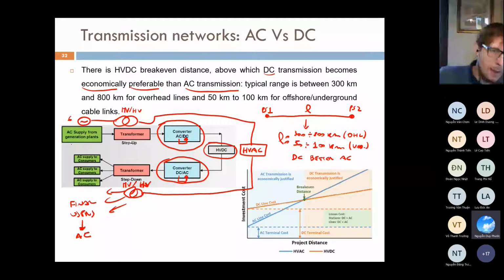The traditional power plants are still in AC. But if you consider, for instance, a photovoltaic power plant, it will be in DC. So if you assume the generation in DC, and let's assume for a second the final users in DC, so you would have lights, refrigerators, ovens, all in DC, you would not have the converters, because you are producing in DC and consuming in DC. You would skip the two converters, and so DC would be very convenient. In that case, DC would win for sure.